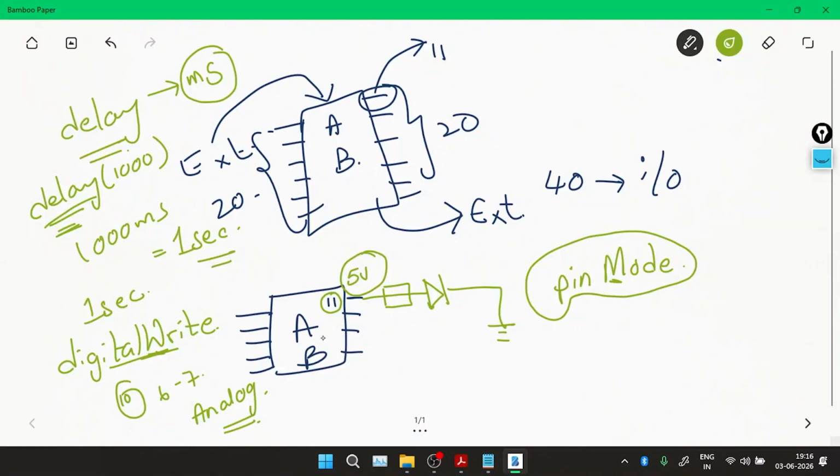See, basically the Arduino board is a digital circuit. It can understand only the language of logic 1 and logic 0. Now in some cases we will have analog sensors to connect to the Arduino board. For those cases we need analog to digital converters, in order to convert the received analog signal from the sensor into a digital signal. What is the main purpose? Because the Arduino board is able to understand only digital logic. It is not able to understand analog logic.